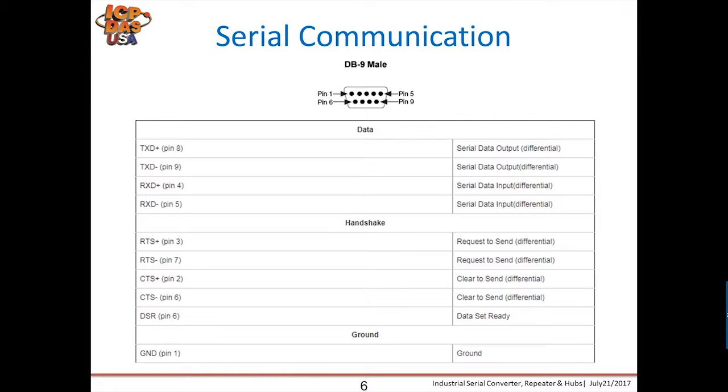RS485 is an improvement over RS422 because it increased the number of devices from 10 to 32 and defines the electrical characteristics necessary to ensure signal voltage under maximum load. With the enhanced multi-drop capability, you can create networks of devices connected to a single RS485 serial port.